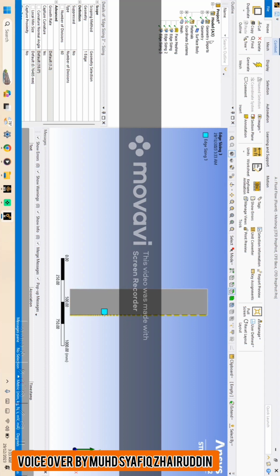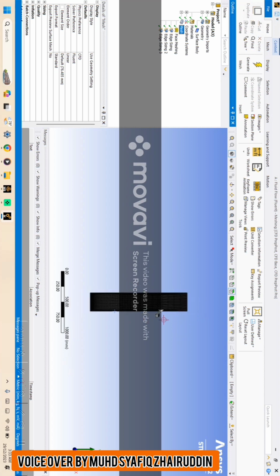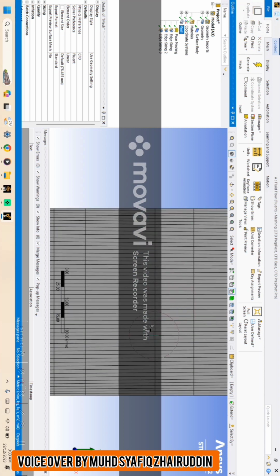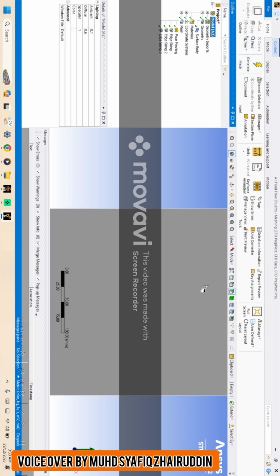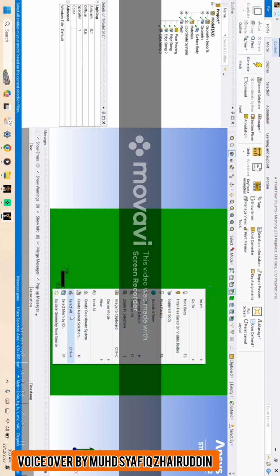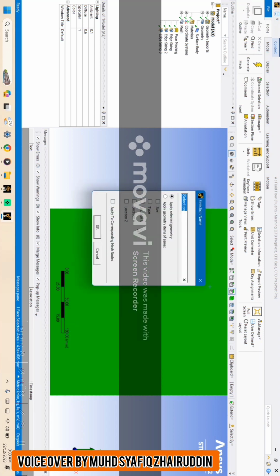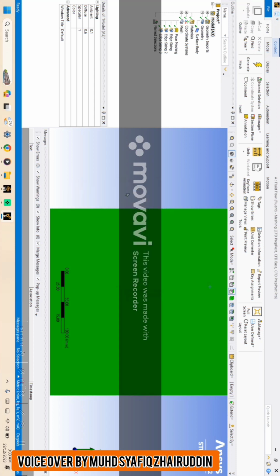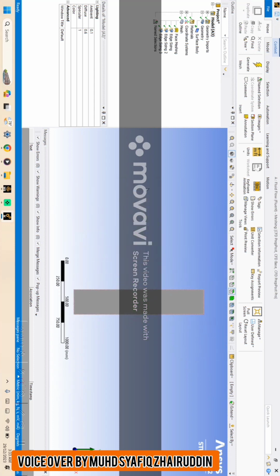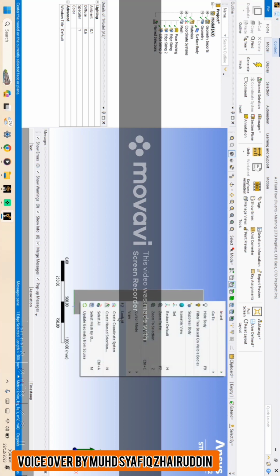Okay, after you are done, you click generate mesh. After you generate the mesh, you click the mesh, and you can see the grid on the surface of the plate. Okay, so you go to the model, click the surface, right click and create a named selection. For the plate, I put the name air floor and click OK, and then you go to the edge icon and click every boundary.